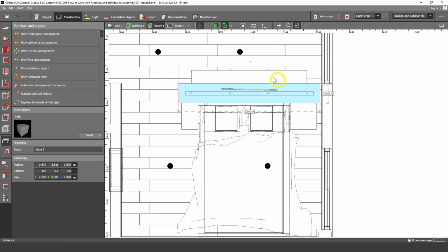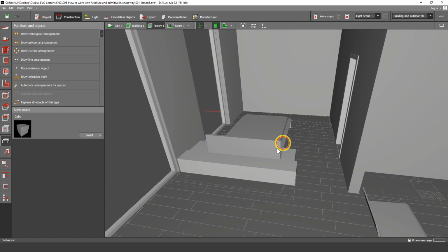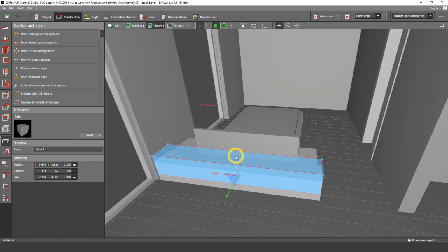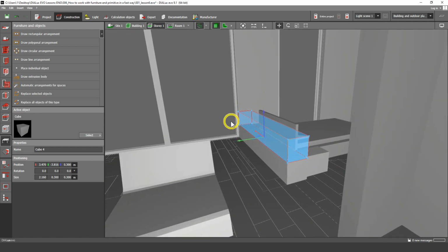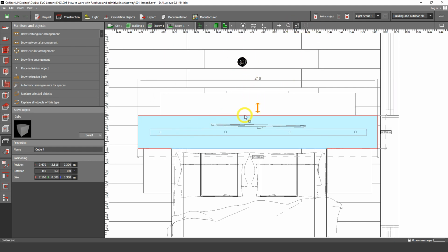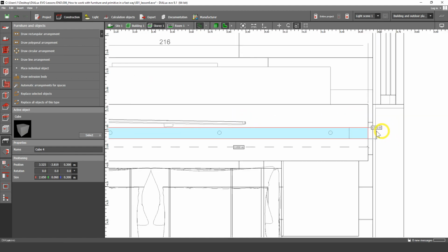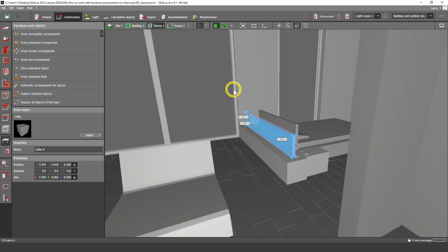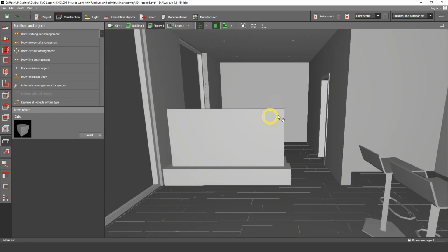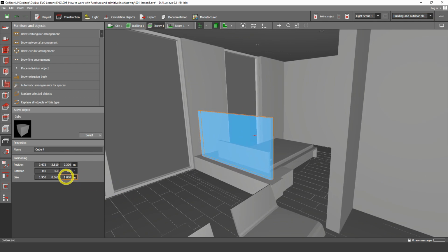So this is like a small wall. Let's copy it. So Ctrl+C, Ctrl+V, using the blue arrow, so I can put it on this shelf, go to the top view, and with the scale tool we can make this small wall like this. Okay, so well, and in the parameter window I'm gonna use 1 meter height. Okay, let's make it just a little bit higher. So let's put here 1.5.